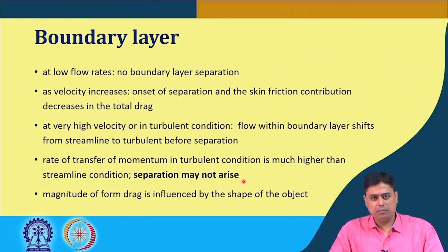So, how has it been done by the scientists? In fact, Prandtl did this by sticking a hoop in front of a sphere when the sphere is submerged and the flow field was coming. So, at the front end of the sphere, if you create some roughness, then that triggers the onset of turbulence and the flow field changes, the boundary layer and all these things get different than the normal scenario, and the drag becomes reduced.